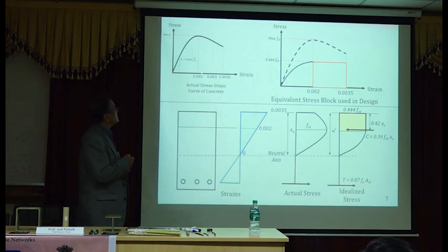So that's the basis for your compressive strength design. For any compression member you are designing, our basis is 0.002. However, for beams, we can utilize a larger strain, which is 0.0035 in case of IS 456. In case of ACI, it's 0.003. Very simple stress strain diagram.